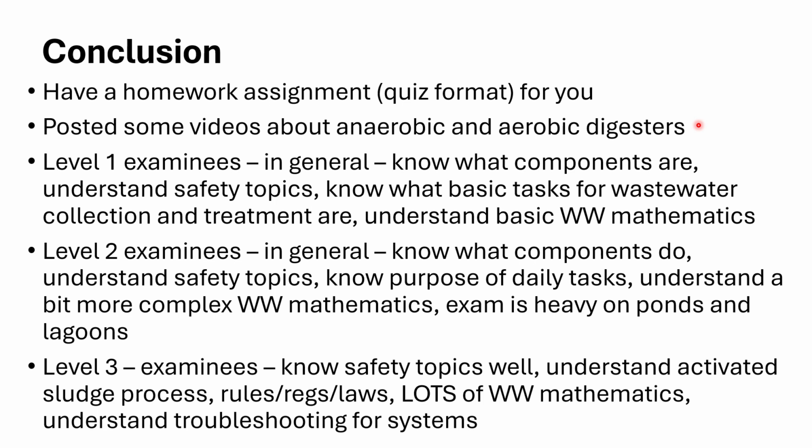Okay. Let's talk about your exam a little bit, not specifically with respect to digesters, but just in how to approach it. If you're a level 1 examinee for the wastewater systems operator, in general, know what the components are, understand safety topics. Your level 1 is going to be heavy on definitions as well. Be able to explain what something is, what a component is. Understand those safety topics. Understand sampling. Understand basic operator tasks like cleaning out the barminator, the comminutor, that kind of stuff. Know how to use a sludge judge, how you would measure a sludge blanket, that kind of stuff.